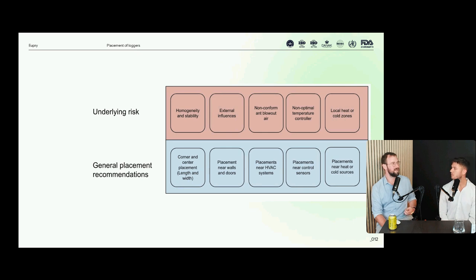I would say the accuracy at which you need to have that data is maybe less. I mean, you could have wider ranges. So normally for any temperature controlled environment, you would need to have a calibrated sensor that is qualified and the system validated to provide accurate data. We don't normally see that requirement imposed on just basically room temperatures, where you want to measure the room temperature just to guarantee that the fridges or freezers were not exposed to extreme temperatures. No, it makes sense.